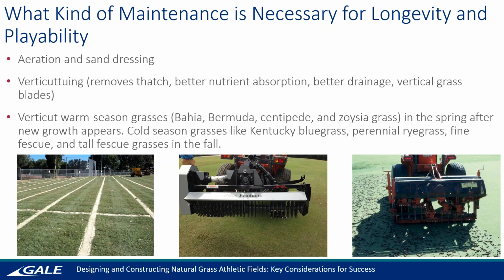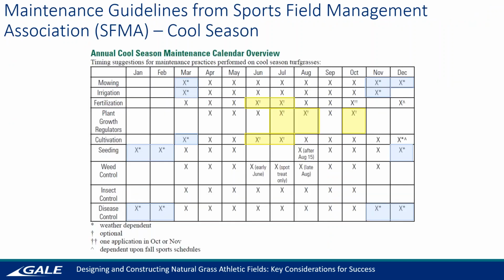If we're having issues with aeration and compaction in native soils, and we don't have a good robust underdrain system, and you don't want to take your field offline to make these repairs, doing the sand slits is a good compromise.